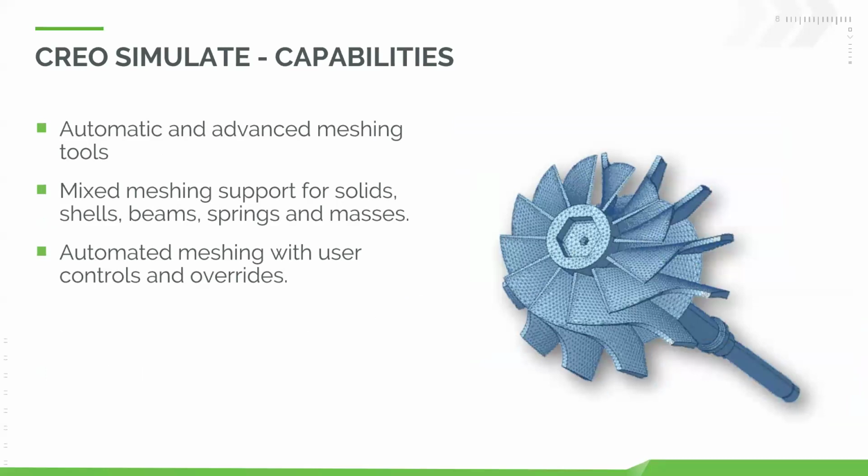As far as setting up the studies in it, it's very straightforward. There's a very straightforward workflow of you would choose the type of analysis that you're performing, then you would go about choosing your loads, your displacements, all of that type of information, your constraints, your materials, and then meshing.